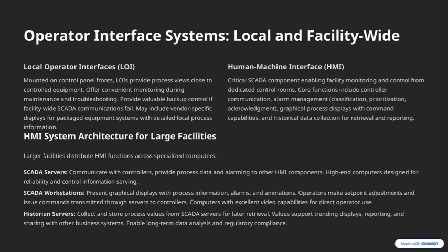Next, the SCADA workstations play a vital role in presenting this information visually. They display graphical views of the process, alarms, and animations, making it easier for operators to understand what's happening. Operators can adjust setpoints and send commands through these workstations, which communicate with the controllers via servers.